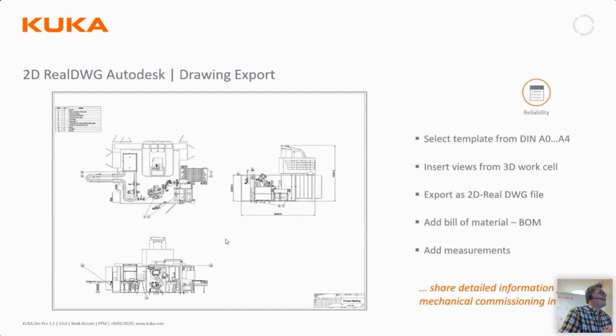Kim has a question. He has tried this and usually imports step files used in layouts, but KUKA.Sim doesn't read the colors, so all his imported items become one-colored. Is there an importable CAD format which KUKA.Sim reads with colors as well?